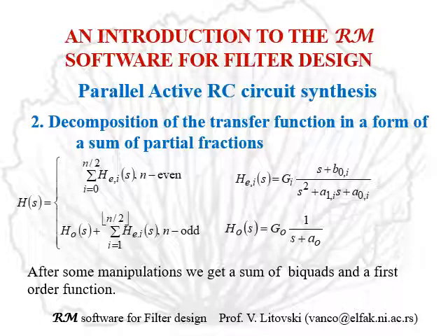Note the second order, no matter where the pole is, always has a numerator which is of first order, and so it is a low pass since its value at infinity is 0, and the slope at infinity is minus 6 decibels per octave.